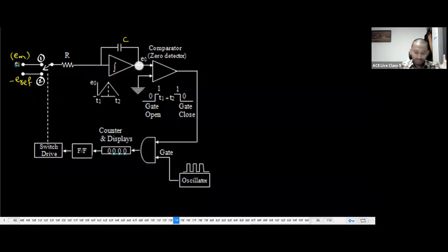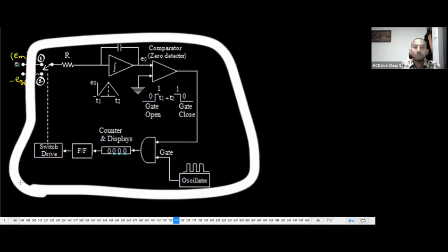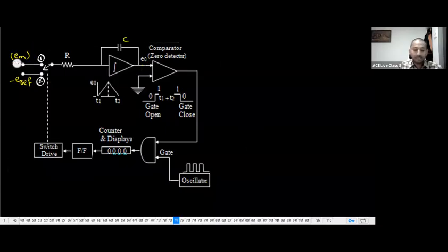Okay. Now, sir, here the input is on. Input is on means after giving the input, and then the input attenuator and range selector switch, it is given to the dual slope ADC. I told you, this entire thing is the dual slope ADC. That input is given. So whatever input we are giving is applied here. This function is to always integrate.